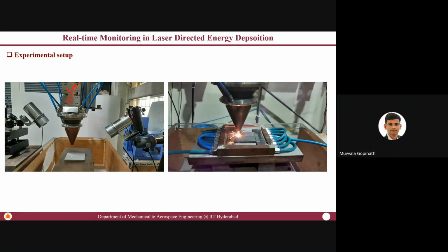Sorry. So over here, you have a DED head. There are 2 IR pyrometers over here. This is IR pyrometer 1 and this is IR pyrometer 2, which are non-contact type. One keeps monitoring the substrate temperature just below the deposition, and the other one moves in that direction, so that as the layer height increases, its height also increases and it takes the temperature from the current layer. That is how it works. And in addition to that, we are also using active cooling, because whatever is feasible, you have to apply.